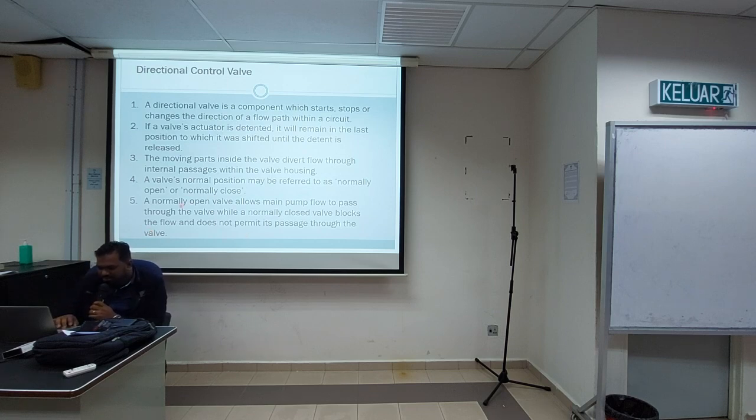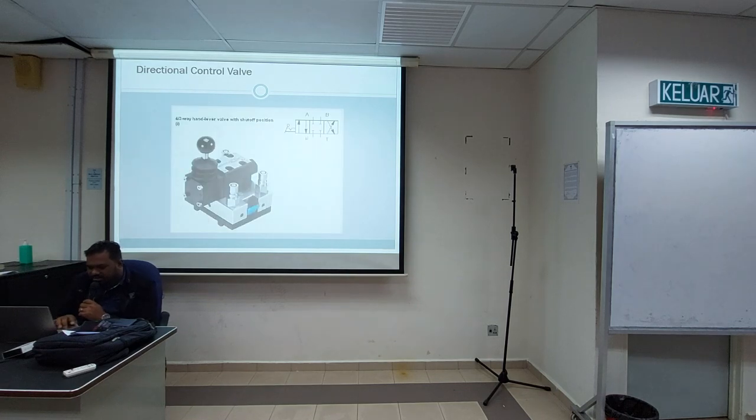So in pneumatic, normally open means normally on. You can remember it: normally open means O, normally on, meaning there will be flow. Normally closed in pneumatic or hydraulic means no connection. There is something we need to know. Later in the slides, I think there is a question on this in the EdPuzzle, so we will discuss further.